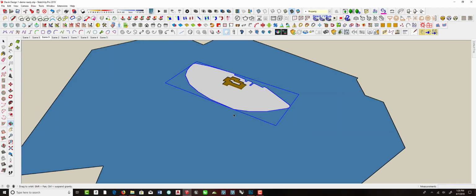If you've already drawn up all your geometry in AutoCAD, you can import that, create the 2D surfaces, and then from that point on, the process is the same. In this case, I'm actually going to trace over a design sketch. And as I start building that in SketchUp, I'll start refining some of those shapes, since it was a freehand sketch.